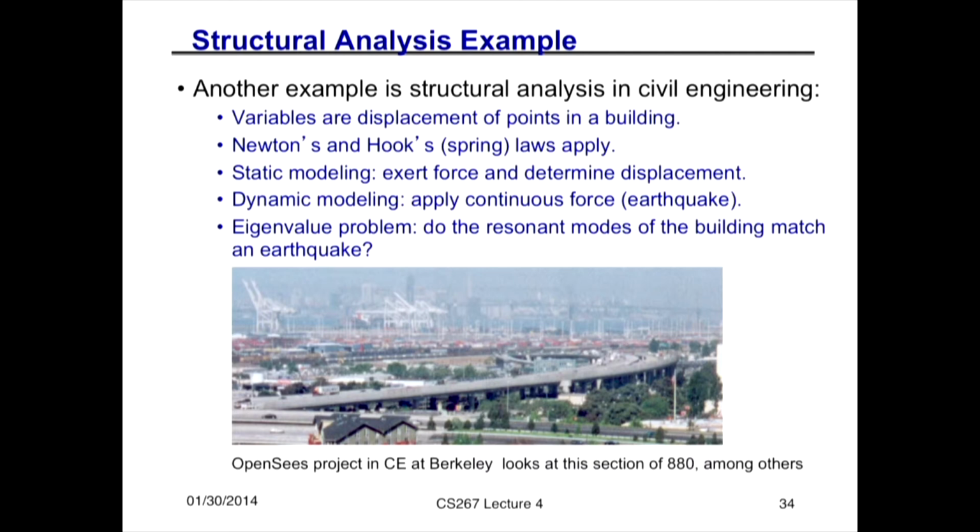A resonant frequency is like a piano string: it's the sound it makes. It likes to vibrate at that frequency. So what you do is you compute the resonant modes at which the building likes to shake, and then you look at historical earthquake data and you ask, at what frequency does the earth like to shake? And if those match, well, you're in trouble, because the building will go into resonance. So that's yet another analysis that people do.